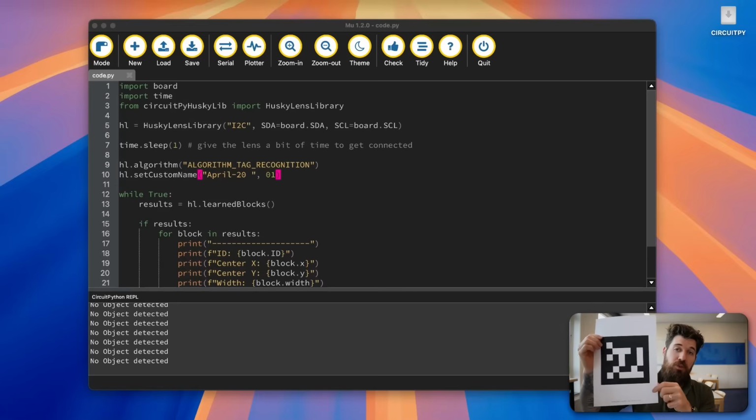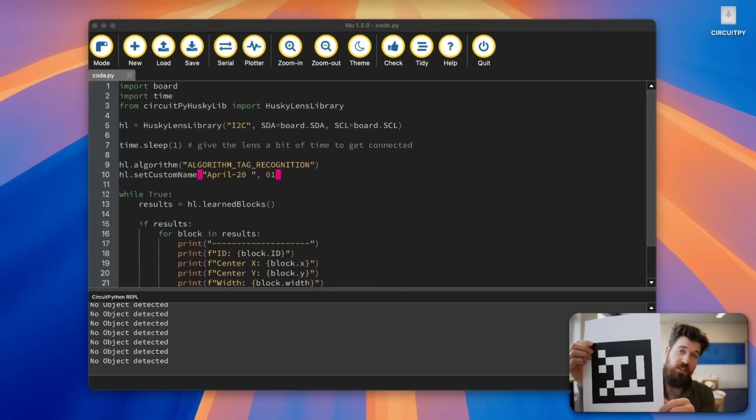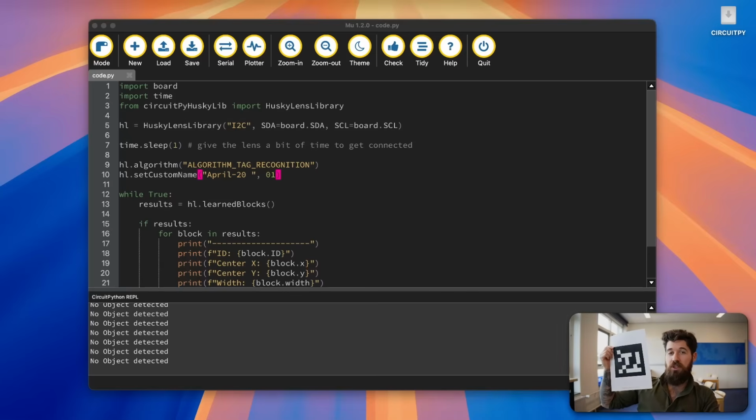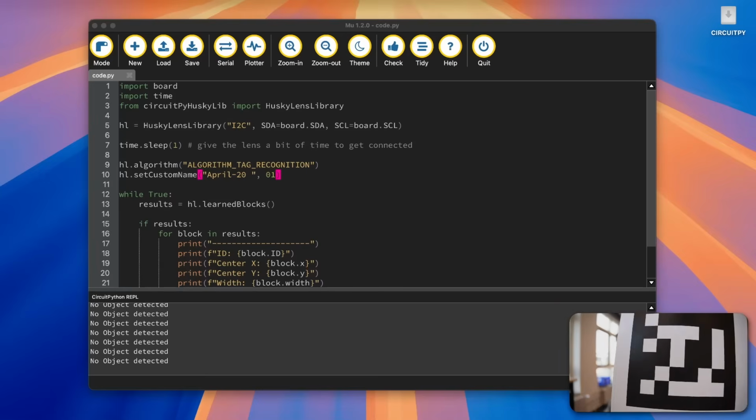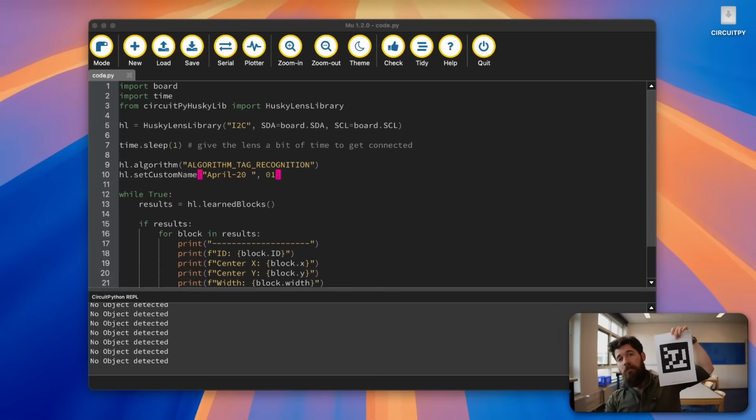And I put the AprilTag at 34 centimeters away from the camera, and then I measured how large the area was. I put it away at 50, and I measured how large the area was. I measured at 100, how large the area was, and so on, at every 50 centimeter point. Then we can log that data down in a table, put it into a power curve equation, and effectively what can happen is as images move away from a camera, the further away it is, the smaller it gets on a square value. So we can actually fit that in a power law curve to be able to get what's called an exponent or a different scale that we can have for our equation.